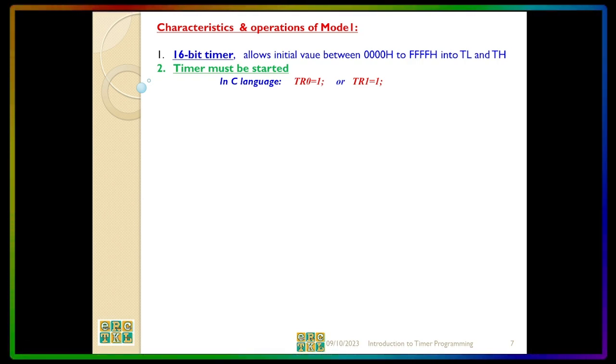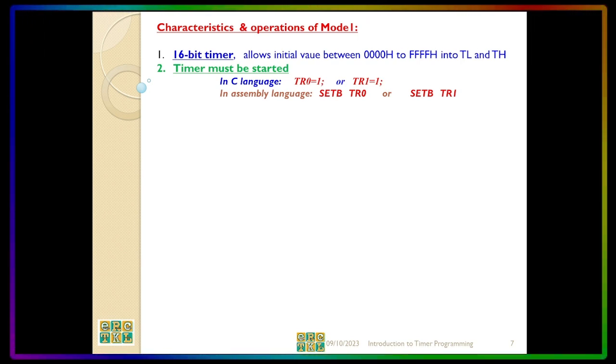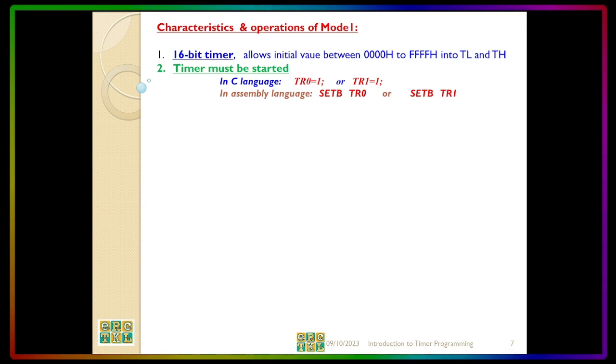Now, there's another language, which is the assembly language. To start the timer, we can write SETB TR0, or we can also write SETB TR1 if we are using timer 1.